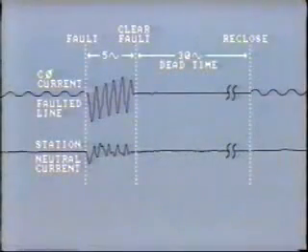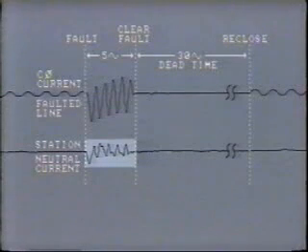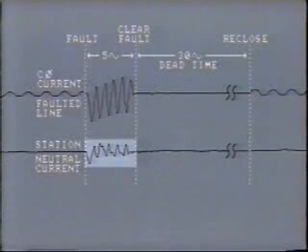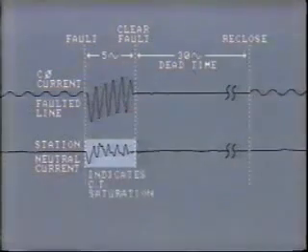So far, the line protection has operated exactly as we would expect. But take a look at the station neutral current. It is extremely distorted and became progressively worse during the 5 cycles that the fault was on. Distortion like this is a clear indication of CT saturation.